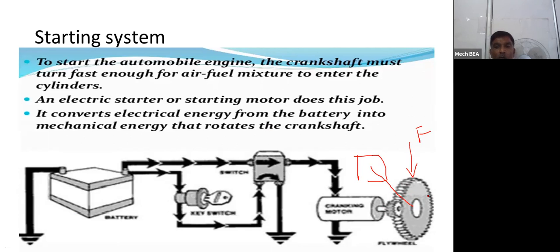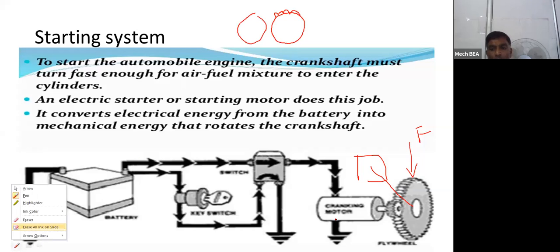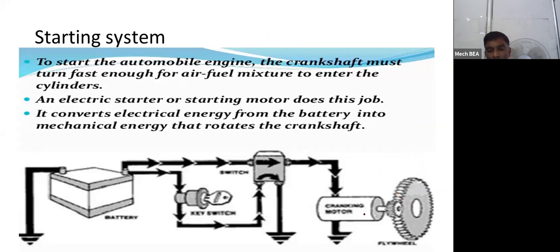That ring gear is provided on the flywheel, and it is in mesh with the pinion of this cranking or starting motor, which will rotate the flywheel.